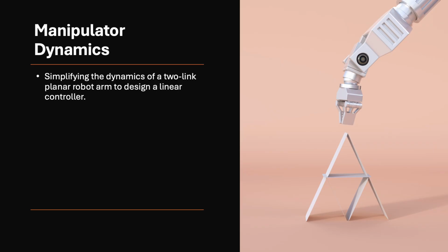In this scenario, the robotic arm must accelerate and decelerate smoothly to follow a predefined path while maintaining the correct orientation for welding. The dynamic model helps in designing control algorithms that compensate for disturbances and ensure stability. For instance, as the arm moves, the changing configuration affects the center of mass and the inertial forces acting on each joint.